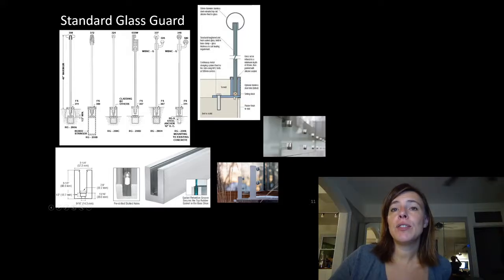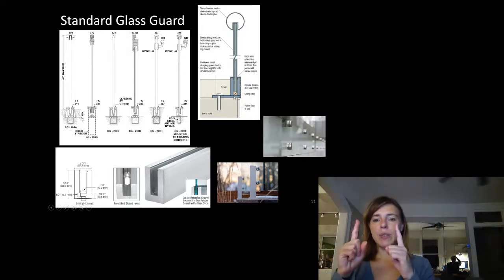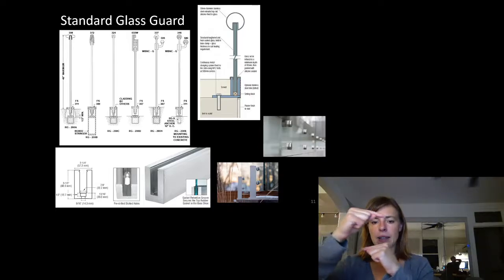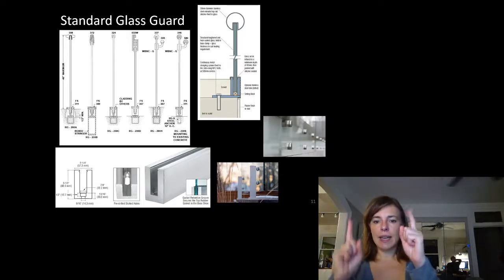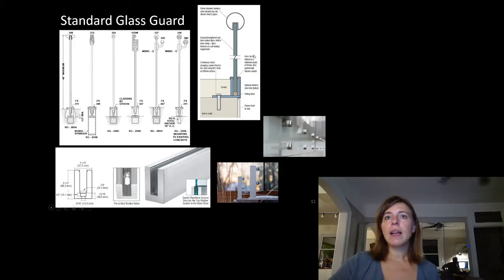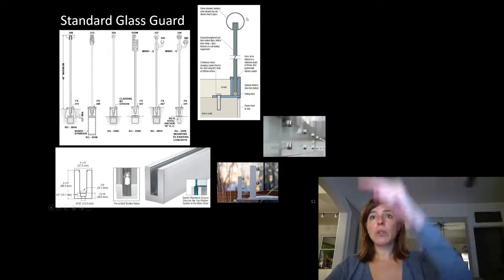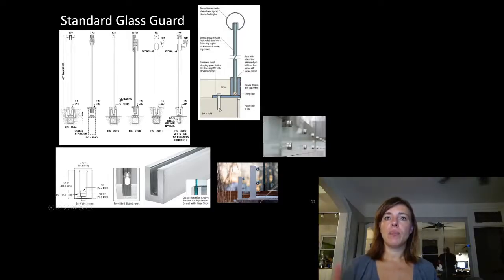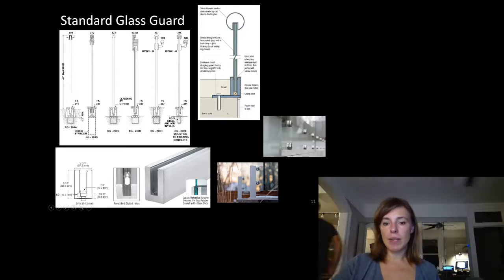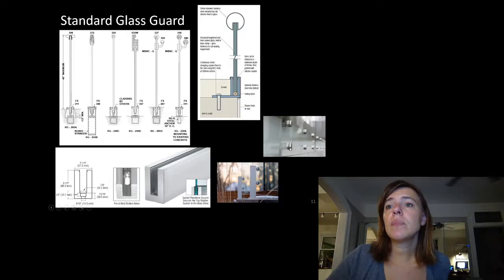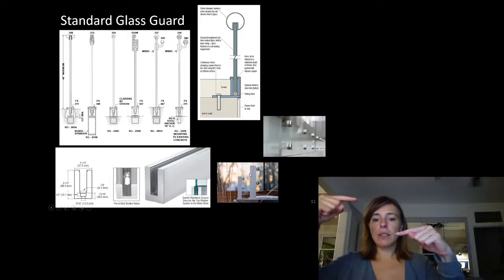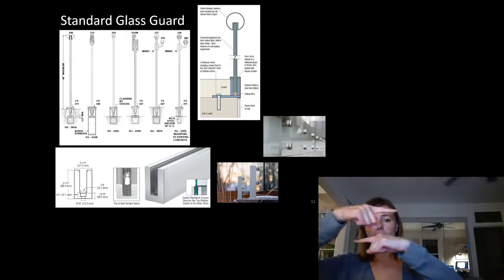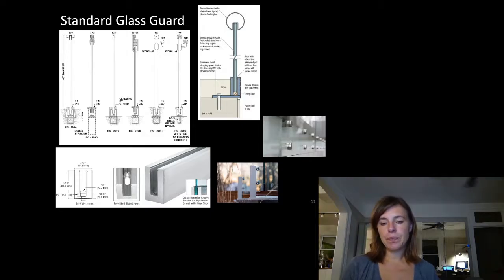This condition here, I didn't draw this free body diagram, but this one, instead of the couple being like this, the couple is like this, or if you wanted to draw it like that. As somebody's pushing out on that top rail, it tries to push down there and tries to pull that screw up. The load is different in reversal, and they've actually designed that as a moment in the reverse condition. Here's the detail at the base for that couple, the way I drew that other free body diagram.